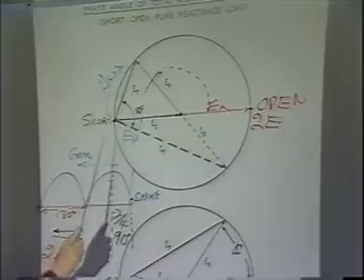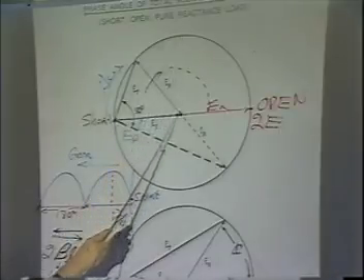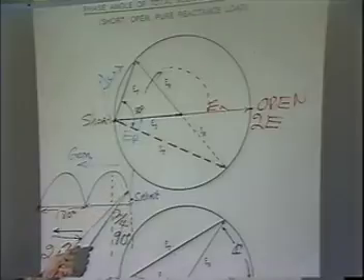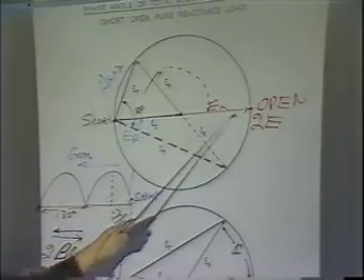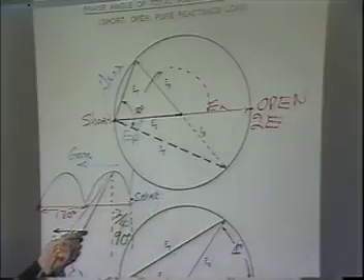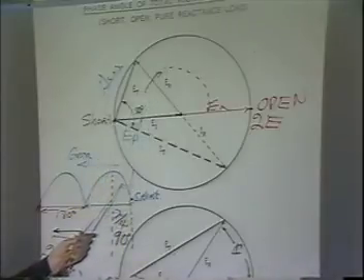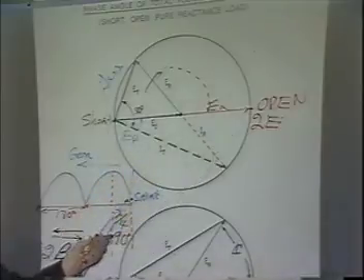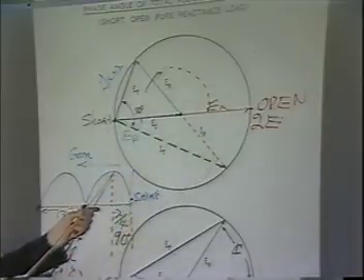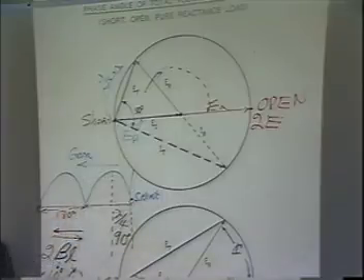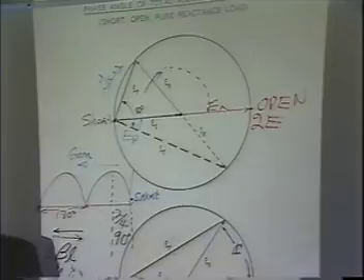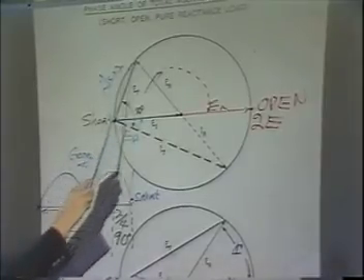So you can see that if I travel on this chart here 45 degrees, I've only gone half that distance on here, haven't I? But when I go over here to 180, I've traveled up to here. Everyone see that? Here, 90 degrees here is 45 degrees here. 180 degrees here, 90 degrees here. Now that's the way this chart is going to represent the transmission line. And every point on this chart, as long as you stay on this circle here, will represent the impedance.